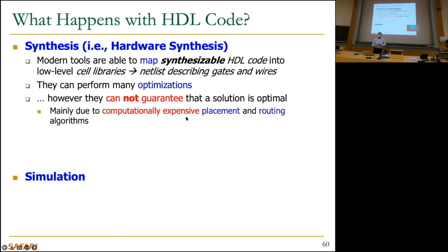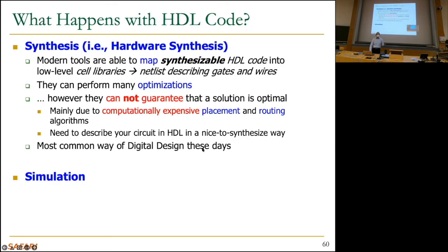And again, the algorithms that are employed in these tools are fascinating, but they're out of the scope of what we're going to see. Just keep in mind that they're computationally expensive. So the placement and routing algorithms are very computationally expensive. So if you really want your circuit to be synthesized nicely, you need to describe your circuit in HDL in a nice synthesizable way. And this is really the most common way of digital design these days.